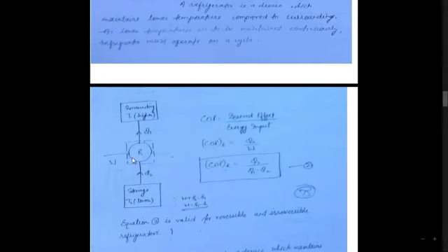In this figure, this is the refrigerator R, and this is the work input W. By adding this work input, Q2 amount of heat is extracted from the storage space, right? What is your storage space? It is the place inside your refrigerator, because you have to maintain the temperature of the refrigerator at a lower temperature. So when the work input or electrical power input is supplied to the refrigerator, Q2 amount of heat is sucked from the storage space, and Q1 amount of heat is rejected to the surroundings.